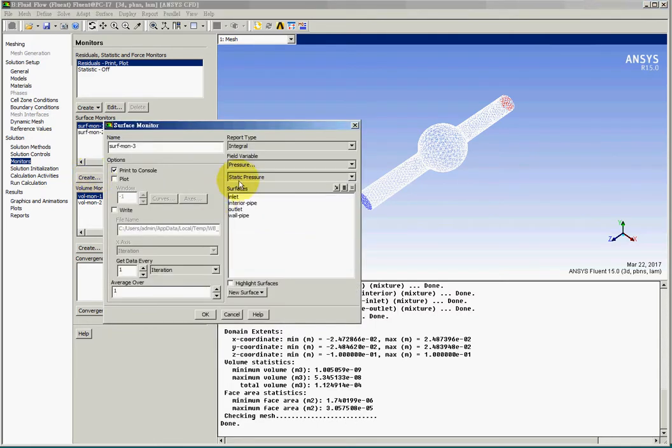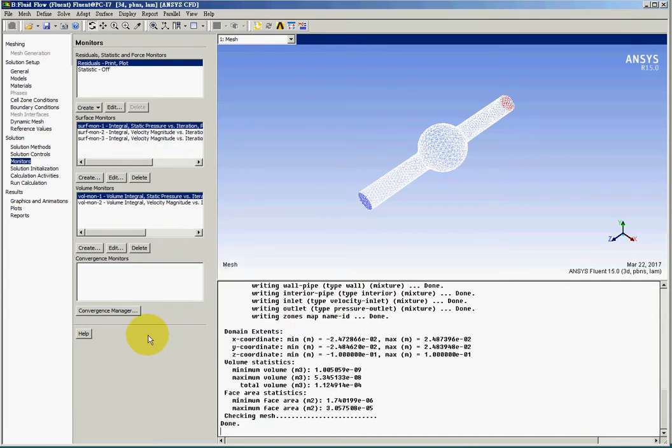We can also create an outlet surface velocity goal, since the velocity is unknown but the pressure is known already, so you don't have to define a pressure goal for it, only velocity is unknown. So we define a velocity goal for outlet and monitor the iterations and convergence of the velocity at outlet in the window 6.